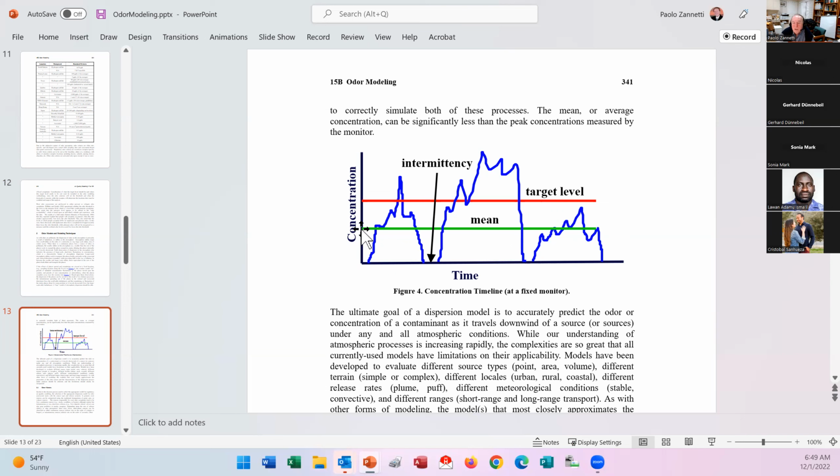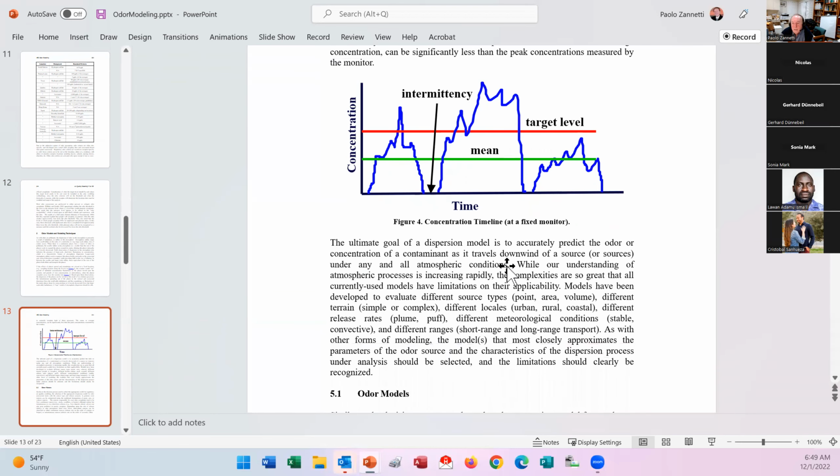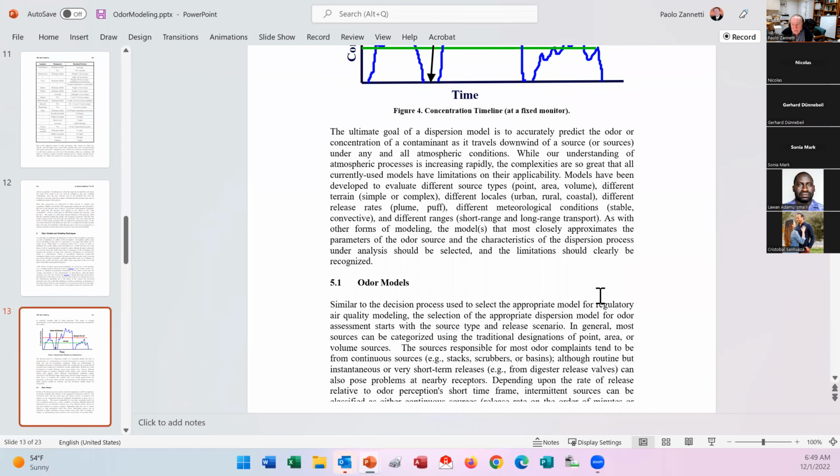If the model simulates hourly average concentrations and the concentration is 100, the maximum concentration during the hour was 160, a factor of 1.6. There are several factors in the literature, but typically I use 1.6 in my studies.